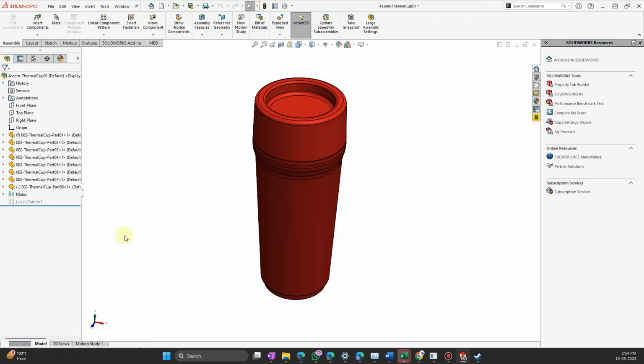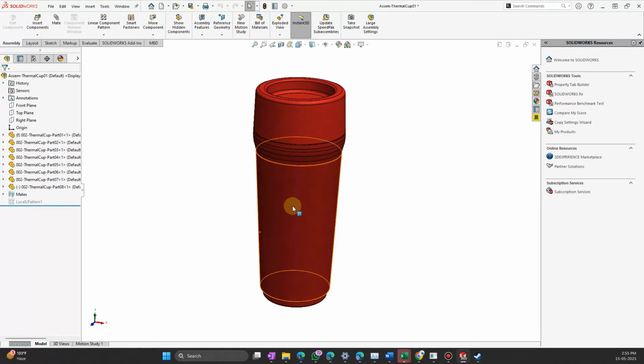Another design standard says that for parts taller than 50 mm, increase the draft angle by 1 degree for every 25 mm. As in, if we're going 75 mm, then the draft angle should be at least 1.5 degrees according to the standards. But there are exceptions as well. The draft angle also depends on the injection molding technology and machines we are using. Moreover, for parts with texture finish, increase the draft angle by 1 to 2 degrees.